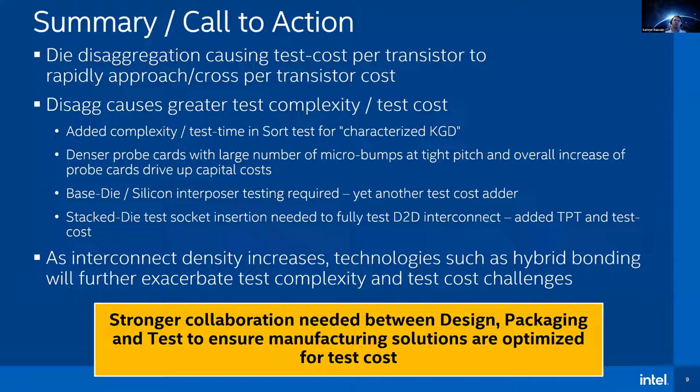the issues that we see are more in the signal integrity space. As we get more and more dense, we might not be able to test all of the bumps on the wafer, and you might have to invest in technologies which don't necessarily contact all the bumps at the same time. But again, that comes with the trade-off that you're now not able to test everything. You might have to reduce your probe count. So different complexities, different trade-offs occur in that space.